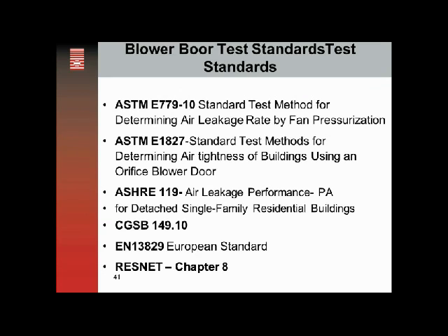All of these test standards are going to have you doing a procedure where you're going to measure the baseline pressure 5 times on a 5-second average. You're going to subtract the lowest from the highest and come up with a range. If the range of those baseline measurements is greater than 5 pascals, you'll be moving into a higher test standard.